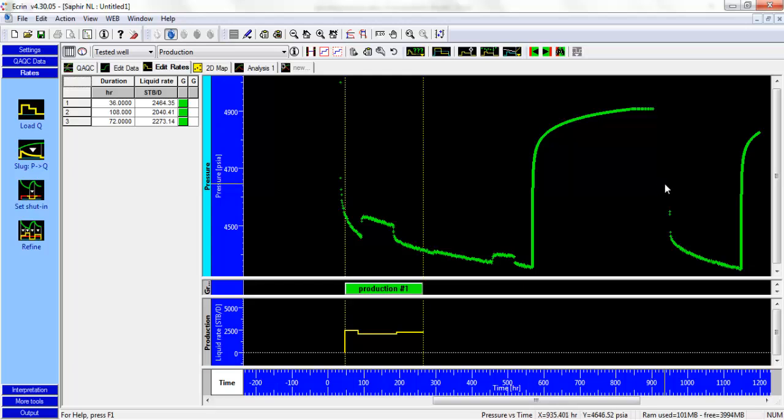If you remember, the gauge were reading some negative values. We'll have to assume the start of the flow rate again around this point here. You can use, for example, the wing valve position to help you. Then you've got a flow period here, and probably more or less at the same rate as this one, and then a rate of 0. You can also QA/QC your rate data once you estimated the rate, comparing the different PBUs.